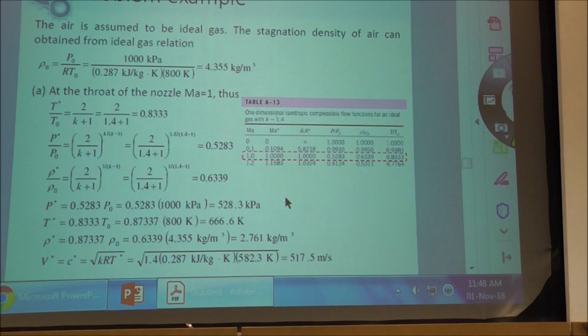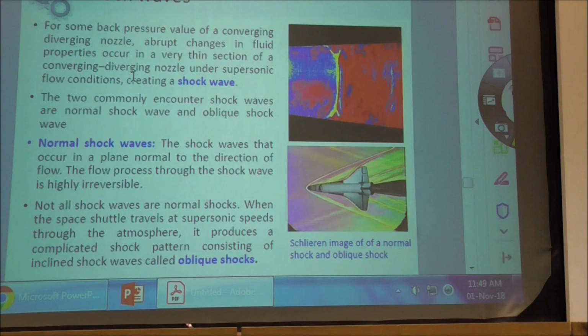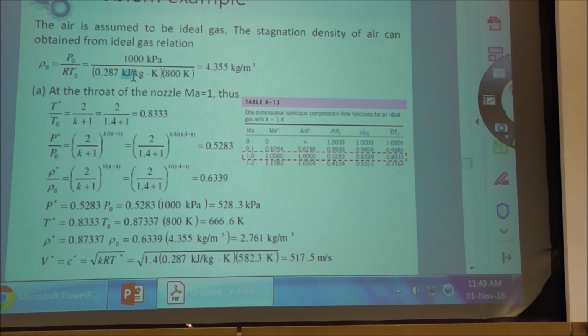The thing that I need to remind you is be careful with the unit. That's why in all my calculation I maintain the unit, because then I know what to do with it. If it is kilojoule, I need to convert it into joule. If it is kilopascal, I need to convert it into pascal. If it is megapascal, you know how to convert it into pascal. Okay? But then in the test, do they use the table or?